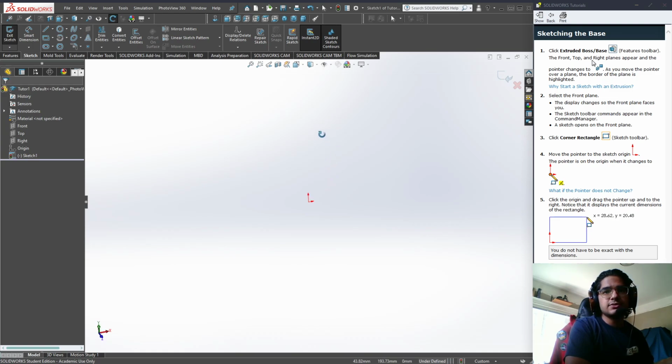By the way, if you want to navigate this, if you middle click and drag around, you get to rotate. And you can see what you're looking at with this little indication on the bottom. So I'm middle clicking, and this will revolve it around the center point. If I press shift middle click, it'll zoom. If I press control middle click, it'll pan. So it all has to do with middle click.